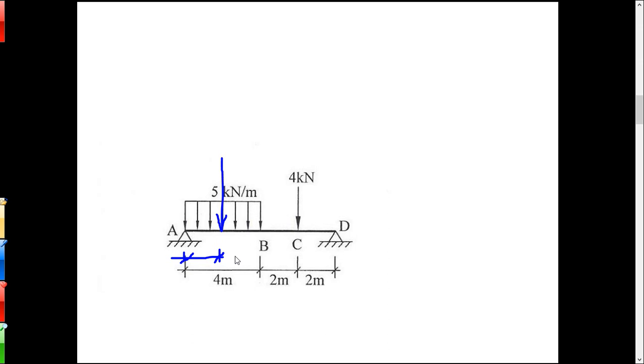Now the answer to that's in the units. You got 5 kilonewtons per meter. That means every meter's got 5 kilonewtons, and that acts over a 4-meter span. Okay. So 5 kilonewtons per meter over 4 meters of length. That'll get you that force, okay? Just turn it into a load and then get the distance that it is. Okay. And this is on 760, the picture is.